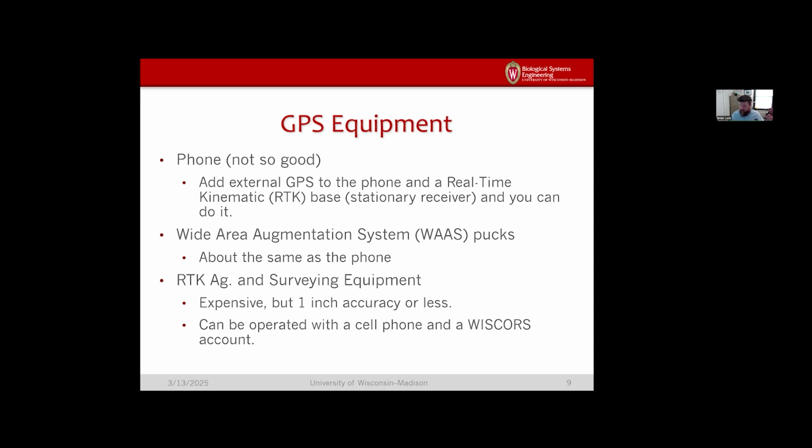So a good 2.5, 3 months have passed, and I would take my receiver on my phone out, and I walk back, and I'm supposed to be right here, and turns out it's 5 rows, 12 rows that way. We have what's called drift with a lower accuracy GPS system. If you're not using that for guidance and you're just trying to find your points, it'll get you within, who knows, probably 12 to 20 feet of where you're supposed to be, and you're gonna have to hunt around for it a little bit.